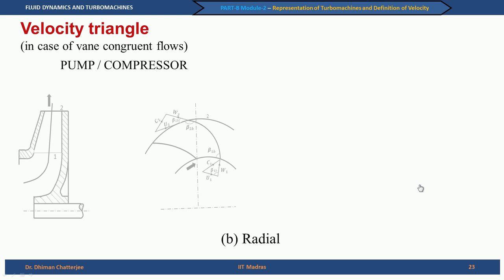In case of radial flow machines, similar pictures can be drawn. This is a direction of rotation, but as you have noticed, in case of radial flow machines, we may not use aerofoil structures, aerofoil cross sections, we may use simply plates which are bent, because that is economical and it serves the purpose. You may need to fillet it to give it a roundedness.